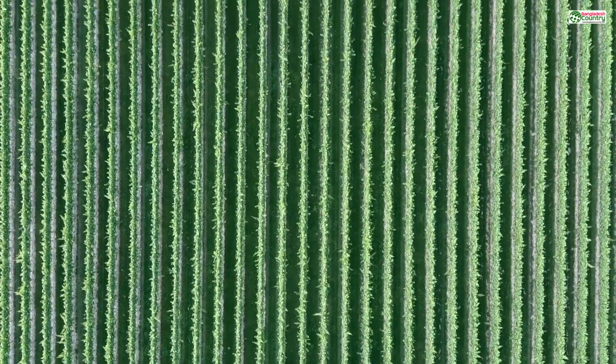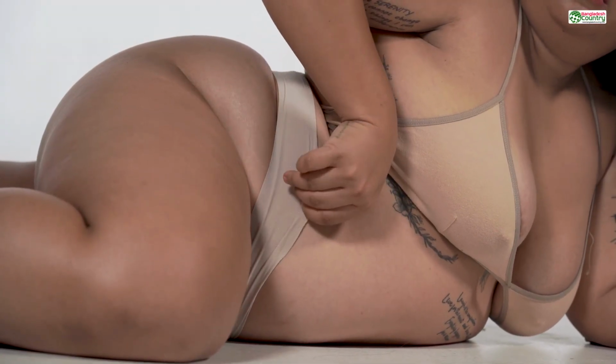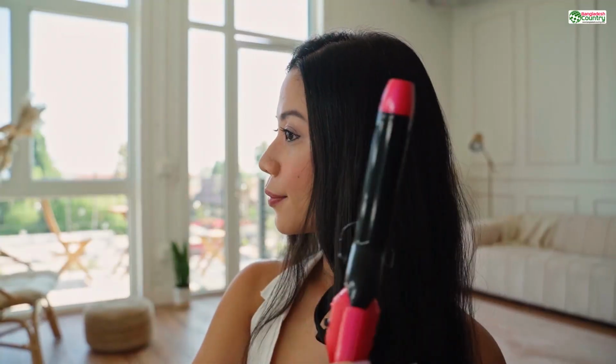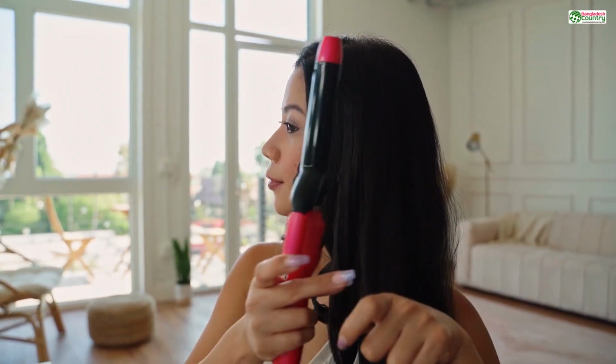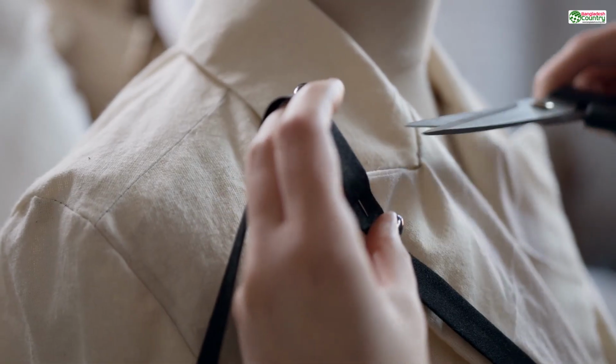With certain materials and large, flat surfaces, overly thick walls can introduce immense internal stress as the part cools down from its printing temperature. This stress can cause the part to warp, curl up at the edges, and ruin its dimensional accuracy. It's like a thick wooden board twisting as it dries. You've made it so strong that it tears itself apart. The goal is not maximum thickness, it's optimal thickness.